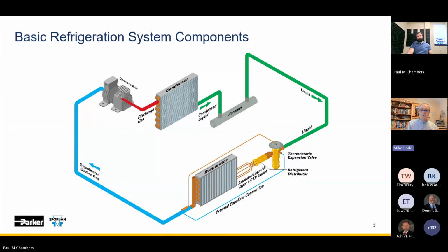It only uses a portion of its condenser surface to condense, and then it further cools and lowers the pressure of the refrigerant. So now we no longer have that high side pressure, the pressure entering the expansion valve that we were designed for. We're not moving the volume of refrigerant through the expansion valve and the evaporator, and now everything acts undersized, basically just because the refrigerant pressure has changed.